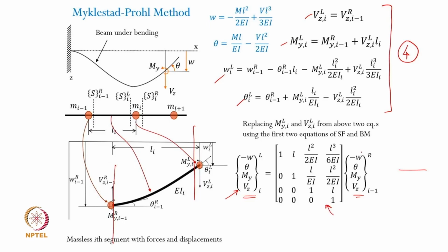Now you would scratch your heads as to this looks a little odd, as to why you have taken this deflection negative, right? But that is mainly for some mathematical simplicity, mathematical adjustment, in the sense that by doing that all these terms in the matrix become all positive, as you can see, right, and it doesn't change anything actually. So there is absolutely nothing wrong in doing that, and you can see that the moment you have this written as negative deflections, you get all the same equations by expanding this matrix. So there is absolutely nothing problematic there. It's just for convenience sake.